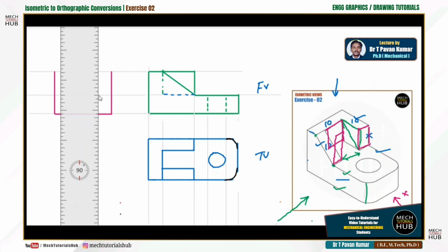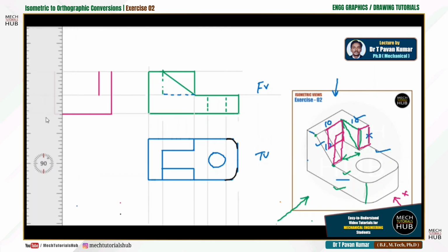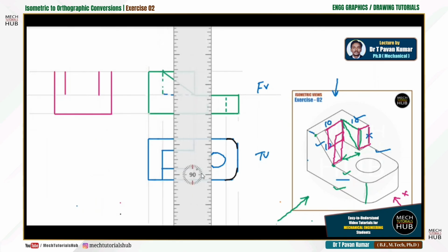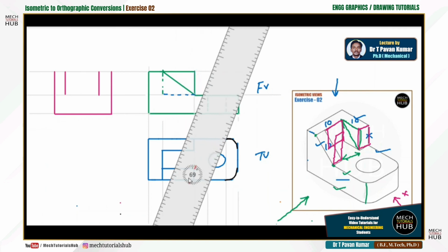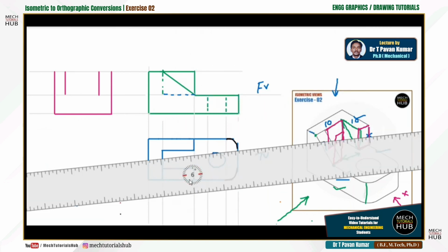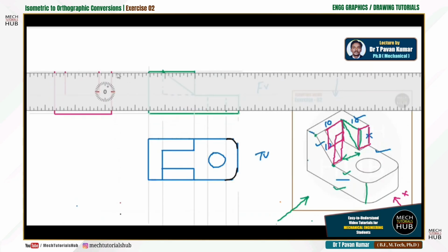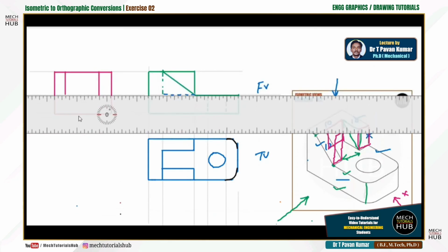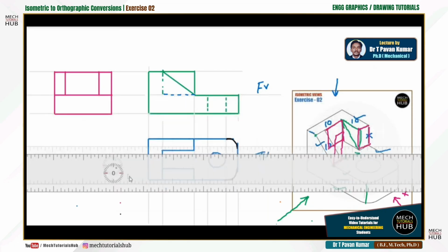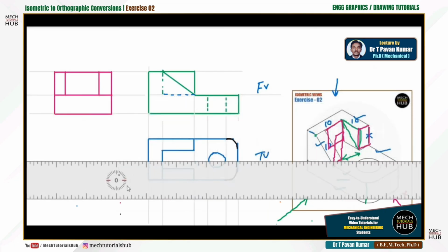So from here, from the top base, I'll take a vertical. To the other side, I'll just maintain 10. Conventionally, I'll just drop a line. Now rotate the drafter scale to 0 alignment or 0 degrees. Then take it onto the intersection and join them all. Done. Take it down again, draw a continuous line. Done. This is how the side view of this particular component looks.